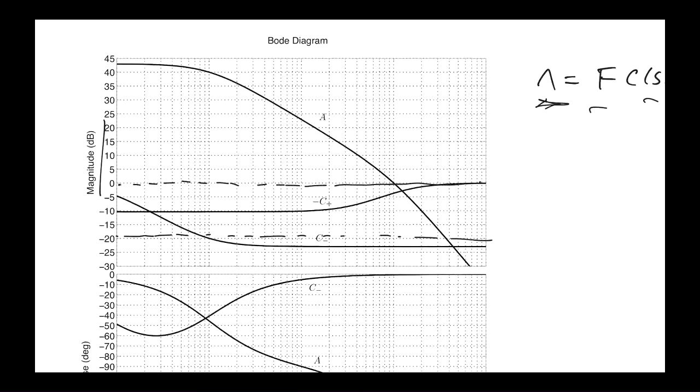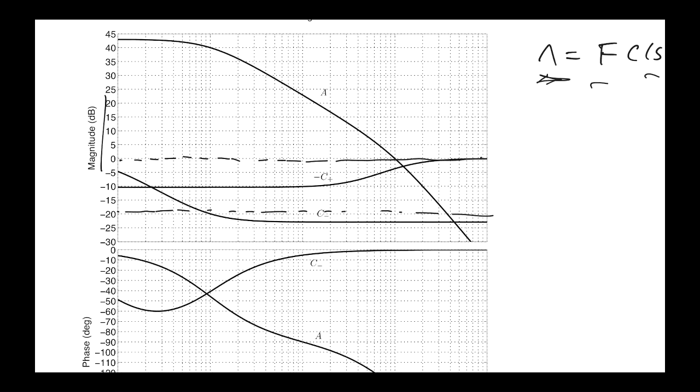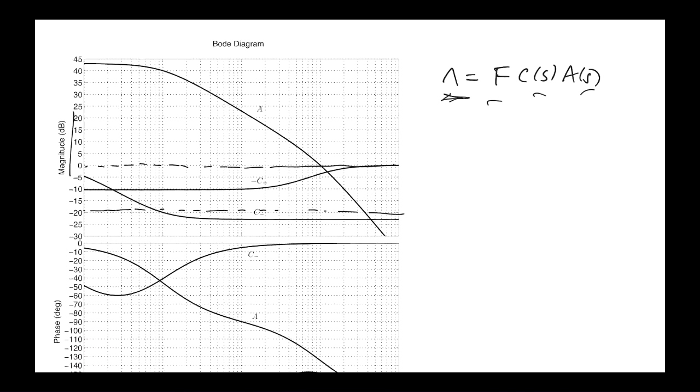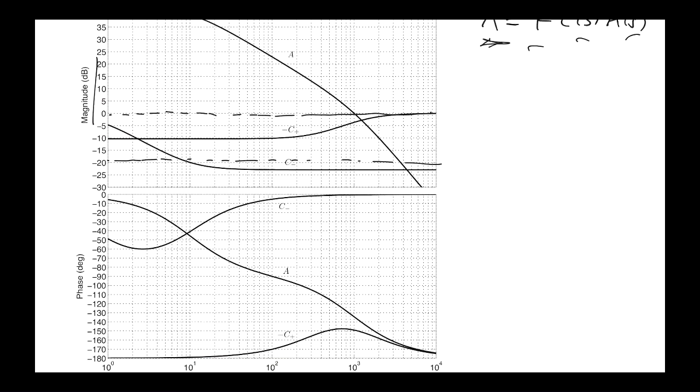We left off looking at the Bode plots for each part, all right? Now, the overall open loop transfer function, which is the product of all these things, can be found by, on the magnitude plot, adding the corresponding bits together. That's what you get when you're working on a log scale, right? The magnitude of the product will be the sum of the magnitudes on the log scale magnitude plot. And similarly, the phase will just be the sum of all the phase components, all right?